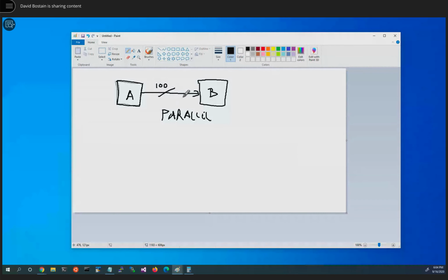However, that's a lot of wiring, particularly in long distance. Let's say this is in one building and this is in another building, and these have to talk, there would be 100 wires running between them if we didn't use some sort of networking to limit it. But minimally, there'd be 100 wires running to something that then networked it and would resume the 100 wires on this end. So let's forget about networking, just say we got 100 wires. Parallel, while fast, is probably not necessarily a really good solution all the time for communicating. Sometimes it is. Old disk drives used to communicate in a parallel fashion with their controller boards. Modern times, though,